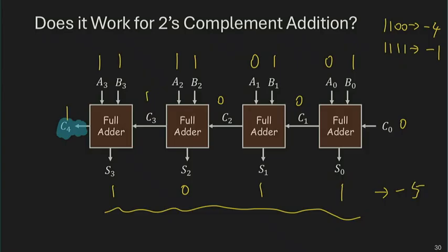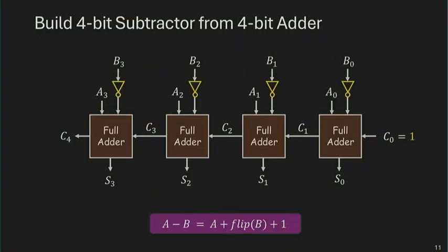All right. So if you need a 4-bit subtractor, one way of doing it is to implement a 1-bit subtractor, as you did in our practice earlier. That's the 1-bit full subtractor. You put 4 of them together, you get a 4-bit subtractor. The other way to do subtraction is by reusing your 4-bit adder.